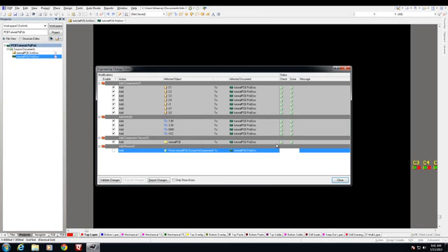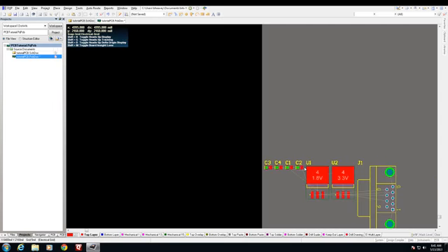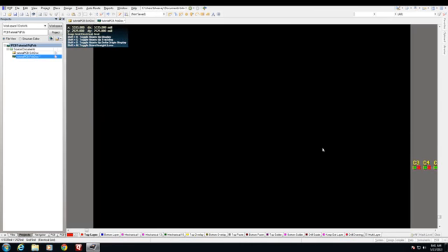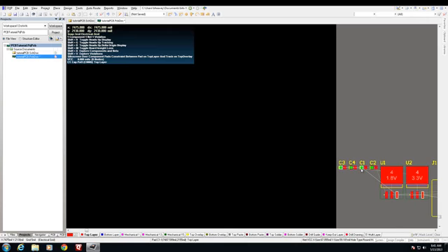All green check marks, which means everything executed properly. Now we can close. So here's our PCB document here that opened automatically once we imported our components. And if we scroll over, we'll see all of the components are now imported into our design. Here are our capacitors, our voltage regulators, and our 9-pin connector. Now that we have all of those components in here, you may notice that a few of the pads are green, which indicates rule violations. So let's go ahead and take a look at the design rules first.